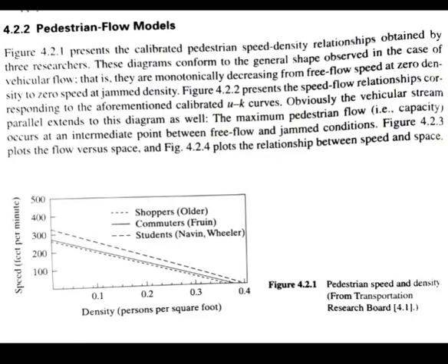And also, what is the width of that particular street? I told you it is 5 meters. So that also you know. Then what was the speed at which they were traveling? So if you know the instant of time, okay, if you divide the number of pedestrians by the width and time, where time here is that particular 1 second, you will get the flow. So it is thus a point measurement in the same way, as I told you before.